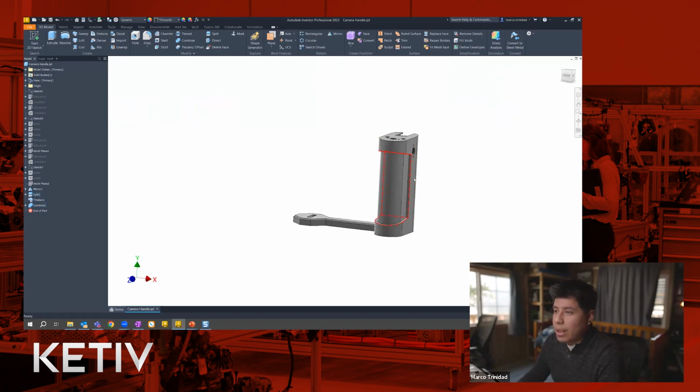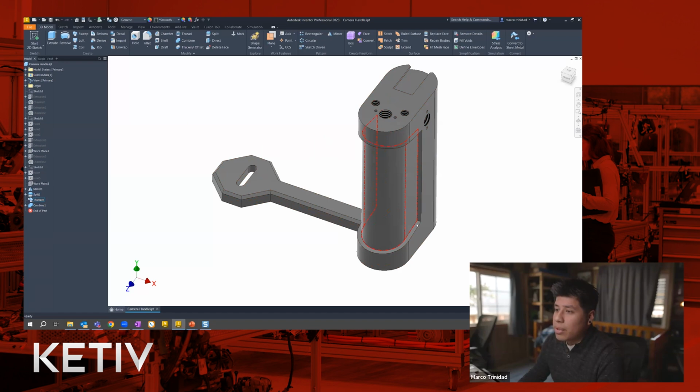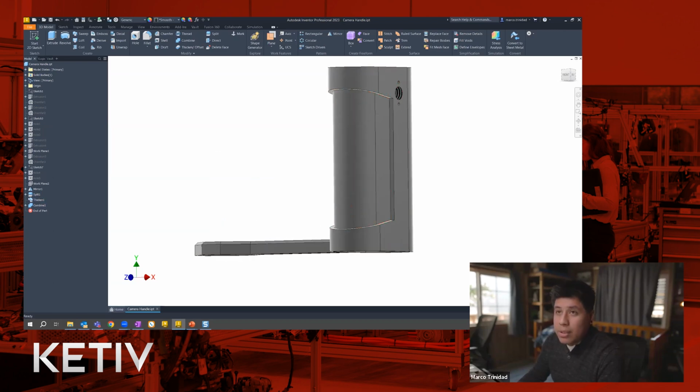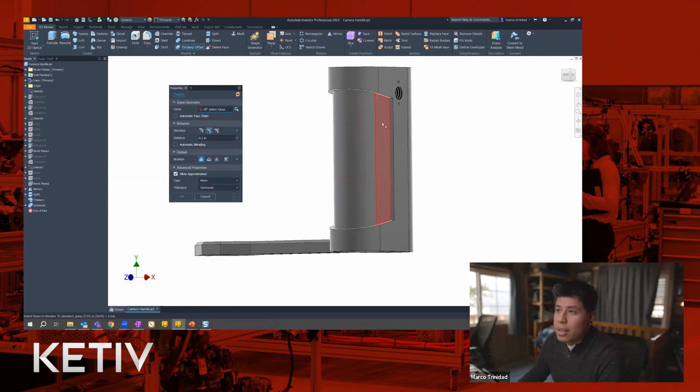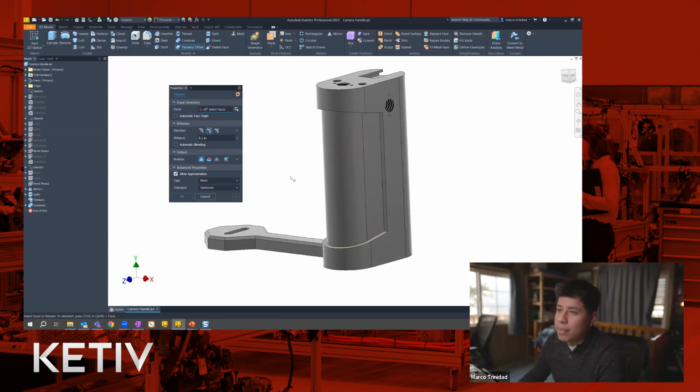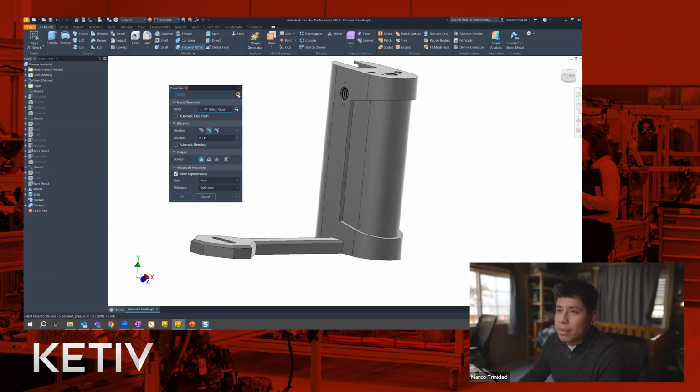And let's say I want to add a grip to this part. So I want to add another solid into this part file with the grip that then would be its own separate part, and I would manufacture separately. So one way I can do that is to go ahead and go inside of the thicken and offset tool. So that's up here in the modify. What I'm going to do, let me pull the window over, is I'm going to grab these 3 surfaces, these 3 faces on my part, and I'm going to create a surface. So the first thing I'm going to do is go up here and turn it onto surface mode.